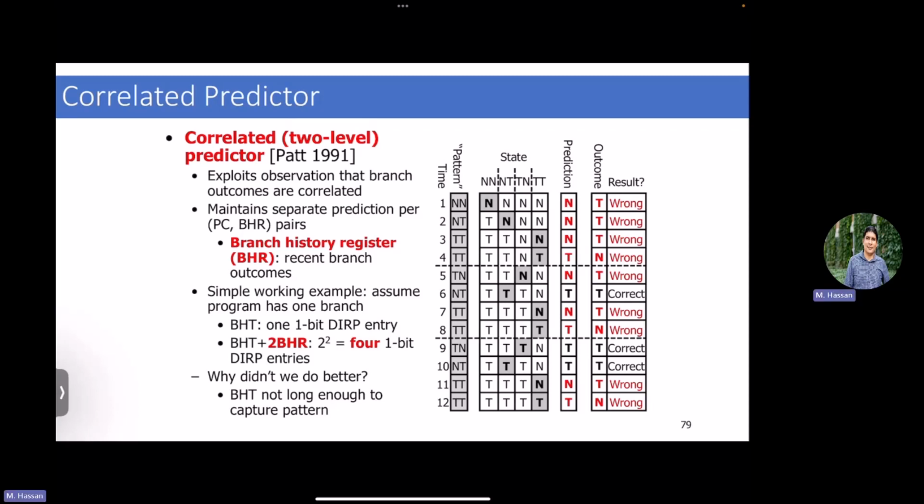So simply, I keep a state of how many bits I am still using. In addition, you still have the 4 bits of the state, but now they are not for the same branch back in the history twice, but they are the direct previous execution of 2 different branches. I don't know if that makes any sense to you.